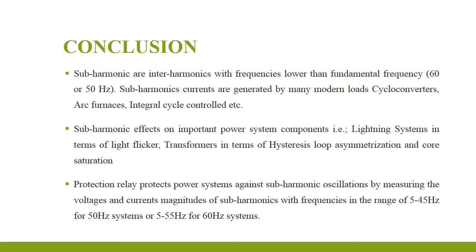Protection relays protect the power system against subharmonic oscillations by measuring the voltage and current magnitudes of subharmonics with frequencies in the range of 5 to 45 Hz for 50 Hz systems or 5 to 55 Hz for 60 Hz systems.